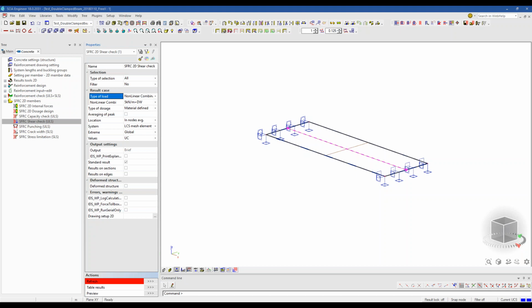This is a very nice remark from someone who is saying we don't need to apply a minimum quantity of traditional reinforcement in case we have a steel fiber concrete. That's fully correct. In case you put the steel fiber in the mixture, then you don't need to put As,min inside your cross section.